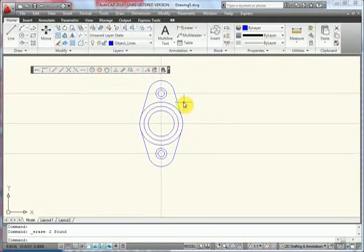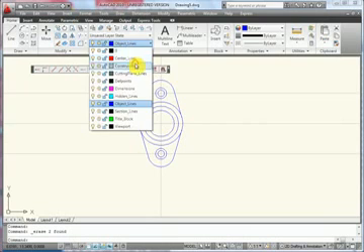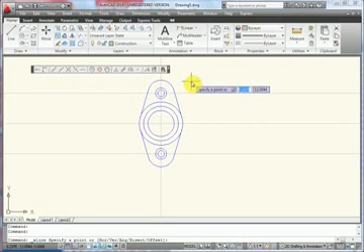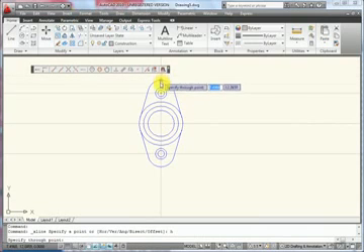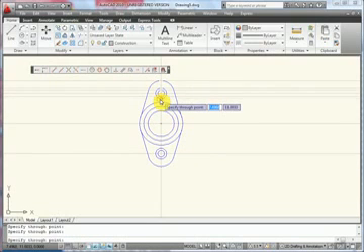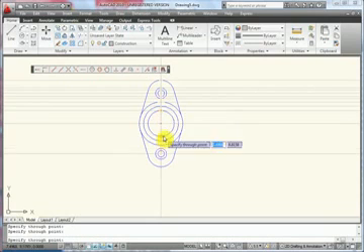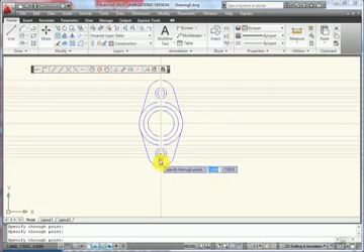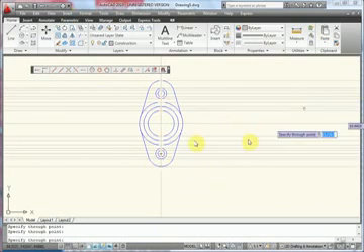So we're going to use construction lines to project over to our side view. So we'll go to the construction layer and we'll get out a few more construction lines. These will all be horizontal, so I'll just use the horizontal portion of the construction line. Now I'm just going to follow down this vertical construction line I made earlier, and anytime there's an intersecting blue line or a center line, or center point, I'm going to snap a line to it. This may look like quite a few lines at first, but if you keep track of it, it'll help you out tremendously. Press the spacebar to end the command.